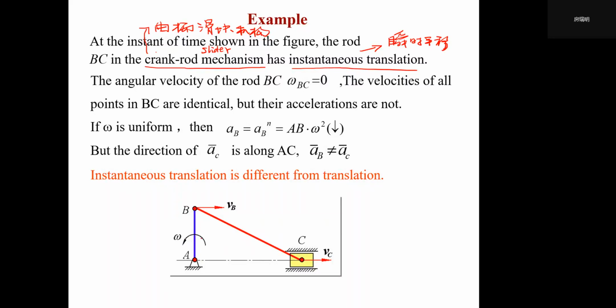So I think actually there's something wrong here. Maybe you get confused, because actually this is not correct. I can just change that: omega actually is CW direction. Then this B will totally go along this direction. Why? We can prolong AB, use the dashed line, and along the direction of omega, I have corrected it into CW direction. Then with 19-degree, we will find VB.